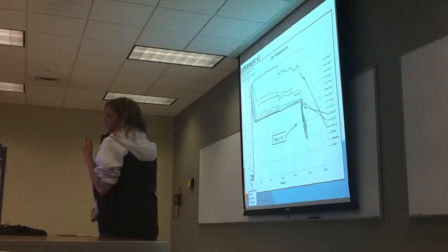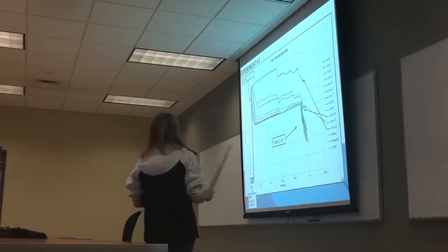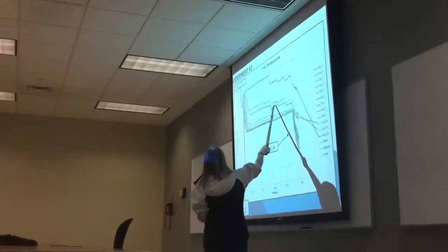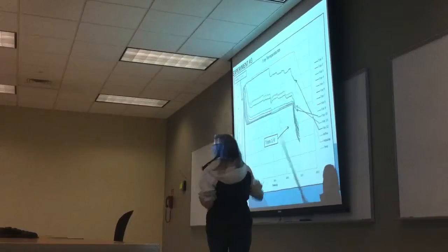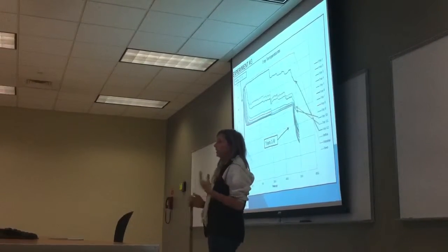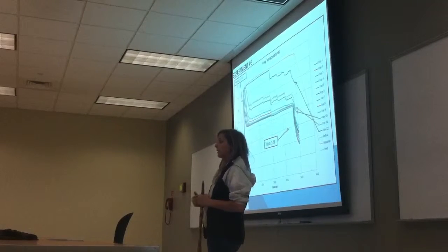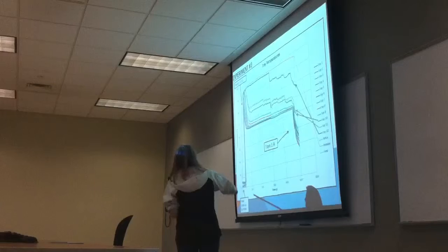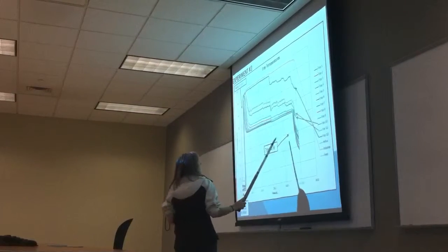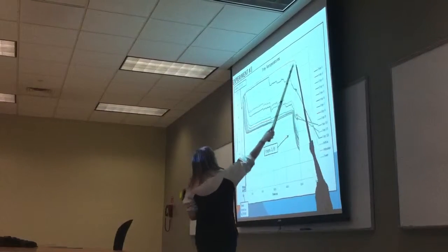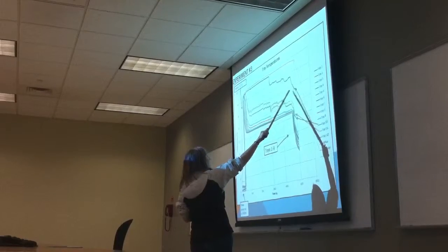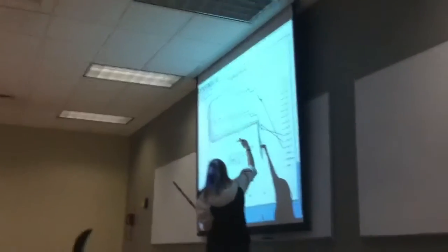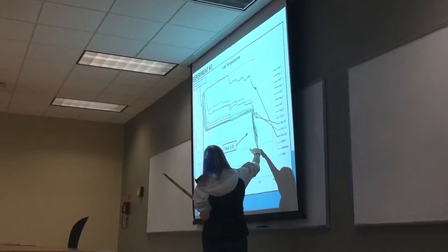The tray temperatures. Notice in this experiment, you can significantly see where the tray temperatures drop off versus the other experiments when we didn't let it run long enough, or we decreased the power wattage too soon. So on here again we have the heating, and then this is your reboiler, and then tray 12, 11, 10, and if you go down, 9, 8, 7, 6, and so on, all the way down to 1.